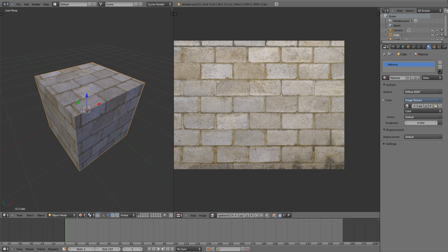You can imagine the seams of Blender just like the seams of your t-shirt. When you have a t-shirt on you, it kind of has a 3D volume to it. But if you were to take scissors and cut it everywhere there's a seam or where the stitching is, then you could lay it out flat into one piece of cloth. This is what Blender does. When you mark a seam, it tries to cut the cube and then flatten it to a 2D object and then project it onto your texture.